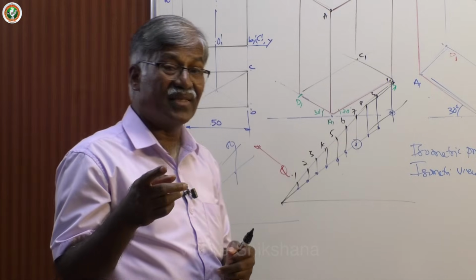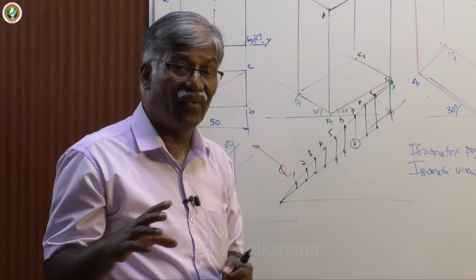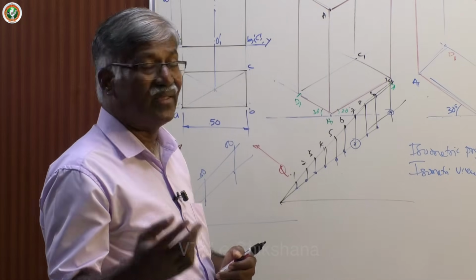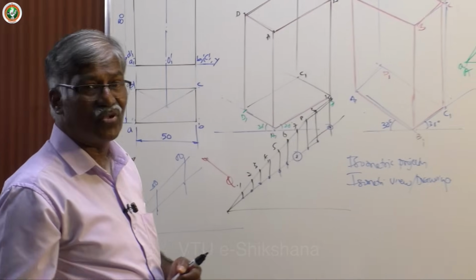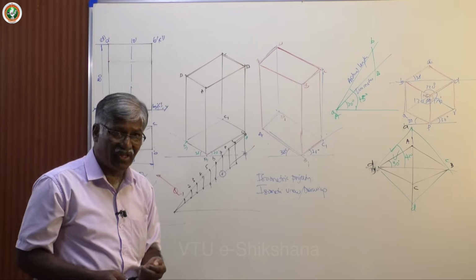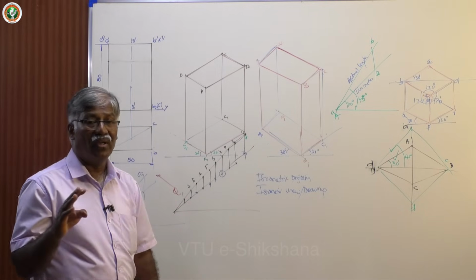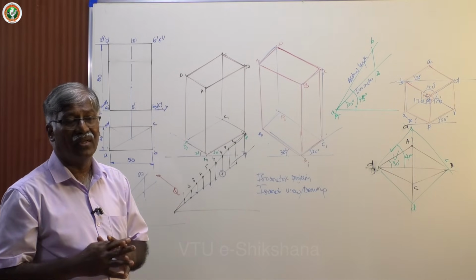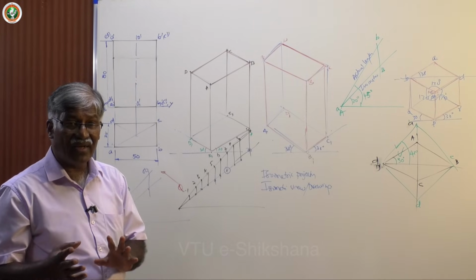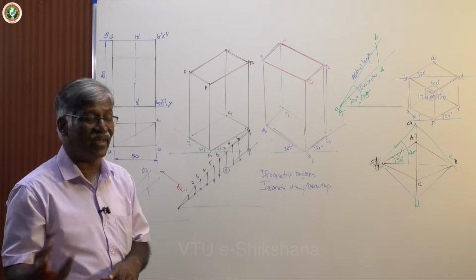But in the case of a sphere, there is a unique procedure, an exception. For a sphere, you don't have an isometric view. That is projection only. I will explain that when I start working the problems on spheres. Now, after this, to draw isometric projection effectively, you should know a minimum of 3 figures. You can say square, rectangle and circle. If you know that, you can definitely work any problem on isometric. Then the derived ones: pentagon, hexagon, triangle, etc.